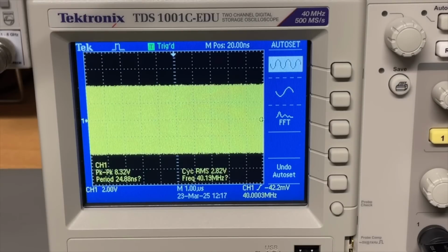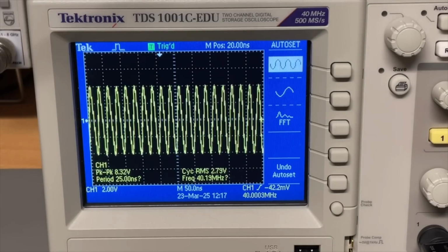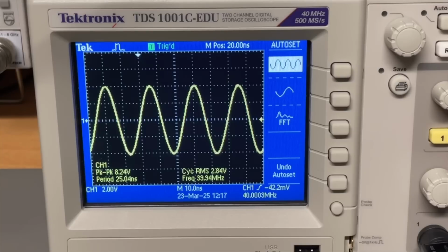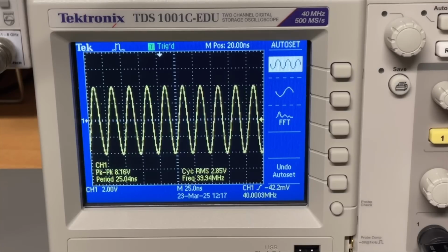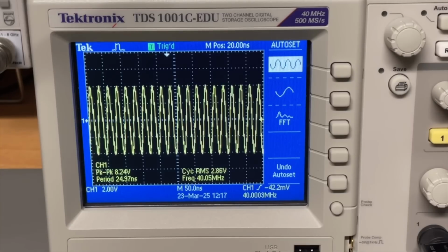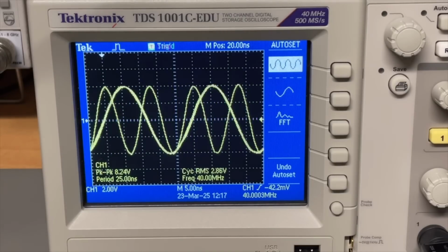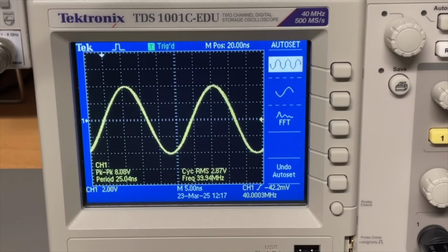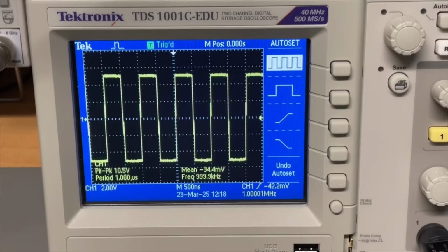So another limitation, but it's more of a practical limitation, is the time base. Can the time base be low enough? Because what if the time base could not go lower than this? It's kind of useless, no? The bandwidth then. But it's a Tektronix, so I trust it will be good. This is the lowest, and indeed this would be very useful. About the square wave, the bandwidth needs to be at least 3 times. I like to show that also.